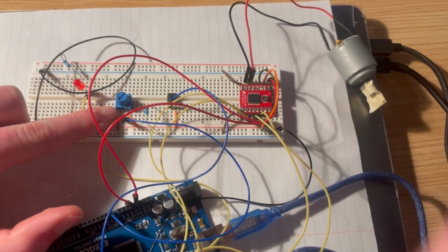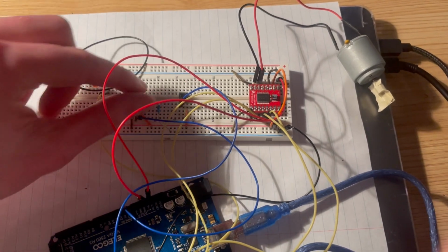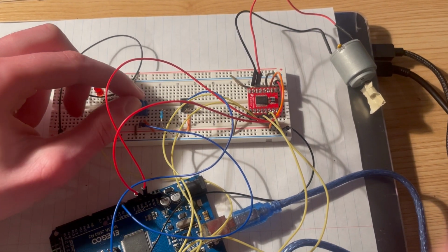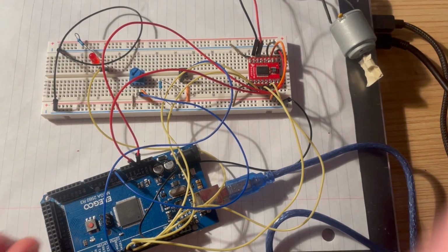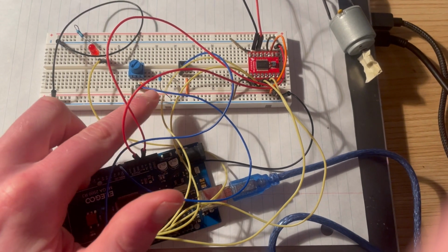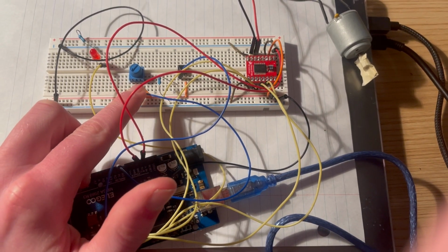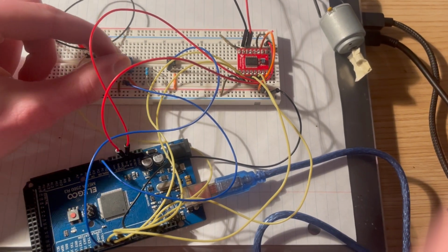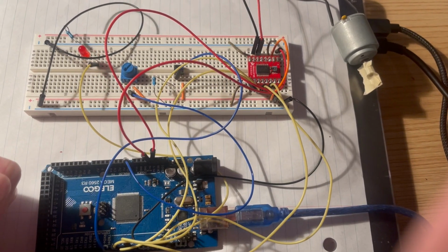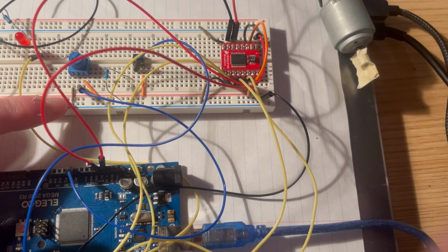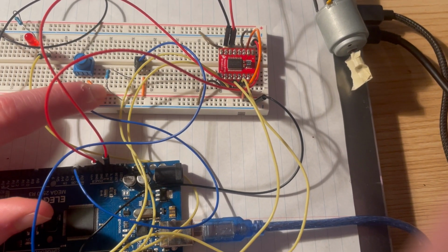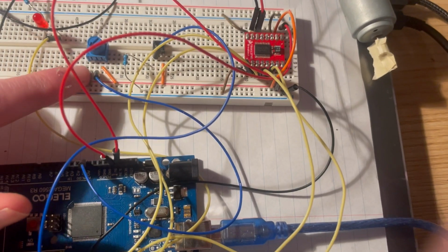We got the potentiometer, and what a potentiometer does is when you turn this knob, it provides more or less resistance on the current going through it, and then the value of that resistance is fed into the Arduino via this blue cable here, and you can use that in your code. So different values are given when this knob turns, and that's how I use it to control the speed of the motor and brightness of the LED.